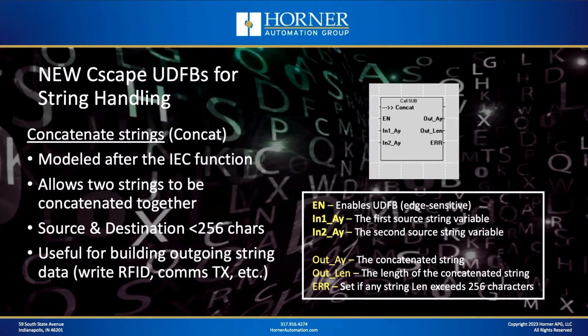We've got a couple more to talk about now, and let's start with the concatenate function. Okay, so this is the concatenate string function. This is a function where you would actually take two existing strings and you would concatenate them into one longer string. Again, there's an IEC function called concatenate, or I think it's abbreviated to concat, that is used for this. And so we've got a UDFB that does the same thing.